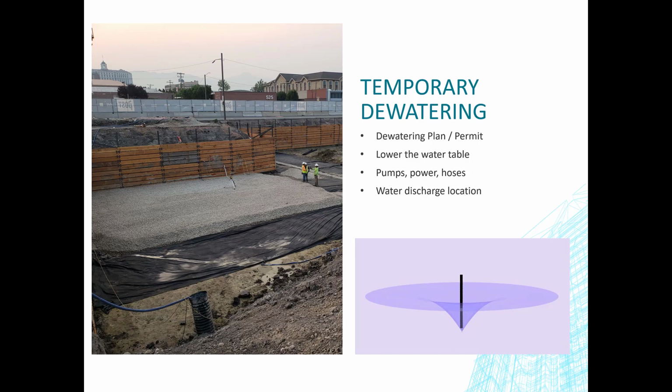So we dug a series of trenches underneath the entire building, lined them with Mirafi fabric, put gravel in them. All those trenches underneath the building, I think they're every 15 feet or something like that. They're the width of a track hoe bucket, so maybe 2.5 feet. And they ran the course of the building. They all collected on the west side, where you had a buried ABS pipe, and then we pumped that.